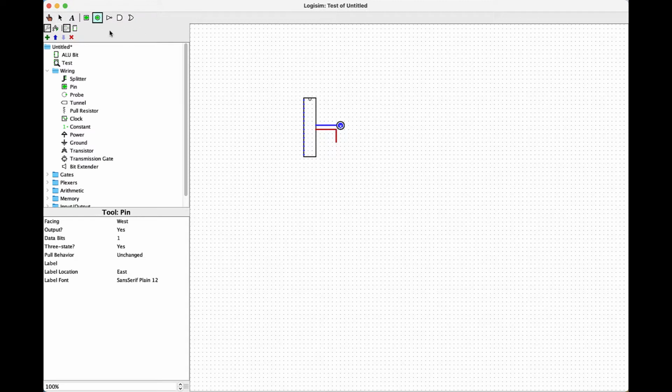You're going to have the C or the bus 3 and the C out output. Go ahead and hook those up, and then hook switches up to all of your different inputs, and then just quickly test out a couple operations, like your add operation. Can you add bus 1 and bus 2 together? Can you add bus 2 and bus 3 together? And so on. Now you don't need to spend a lot of time on that.